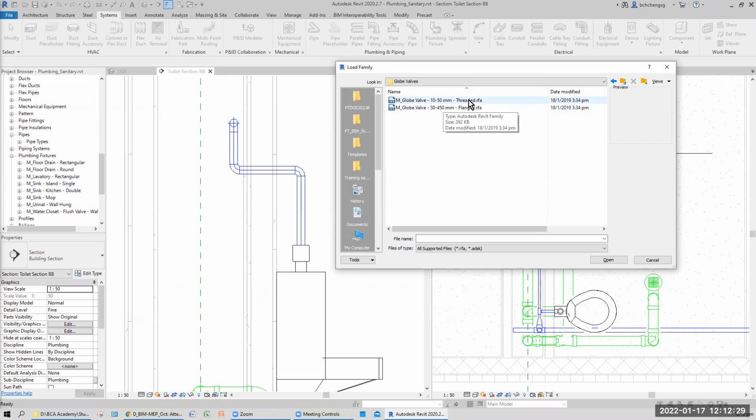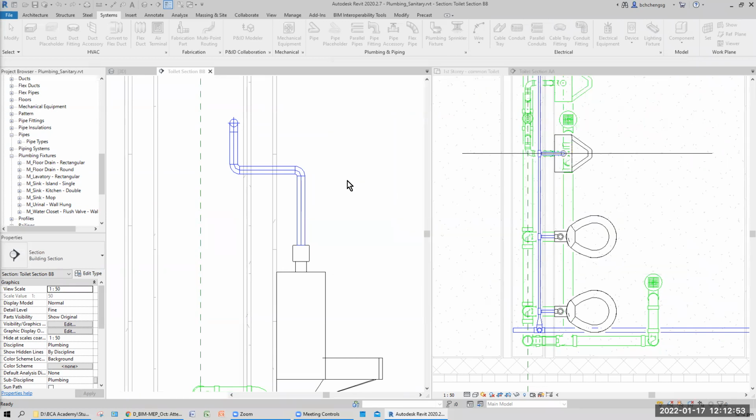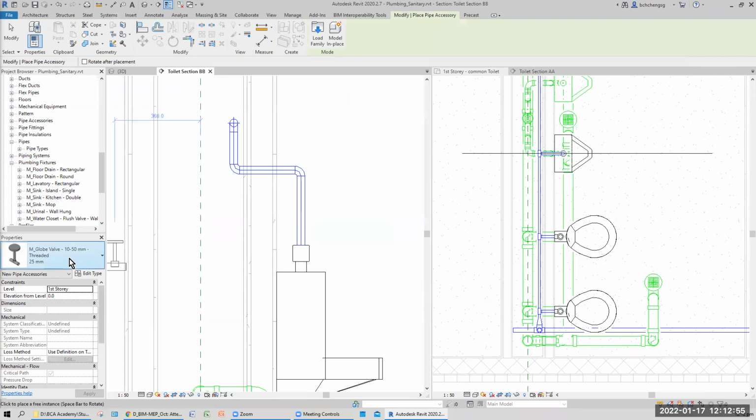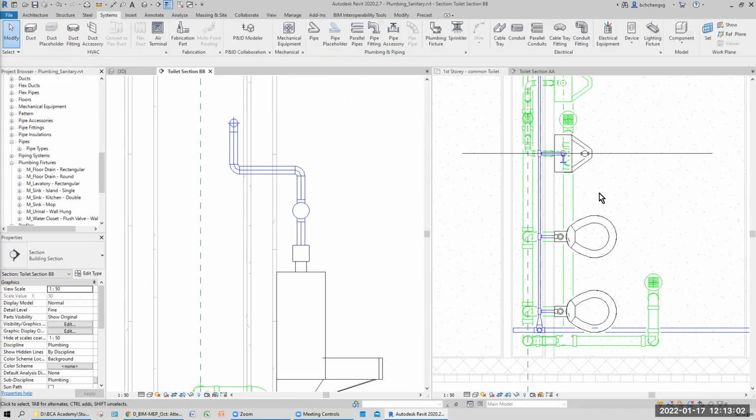So here, I will not talk about the accuracy, whether this is whatever valve. As long as size is concerned, we can use it. I'm happy with it. Because this library doesn't come with a standard component for this particular usage. Okay. So I'll select the valve that can give me the size. That's what I want. Open. Sorry, select first. Open. You load it in, choose the correct size, which is 25, and you insert it in. Insert. Then you do the rotation.